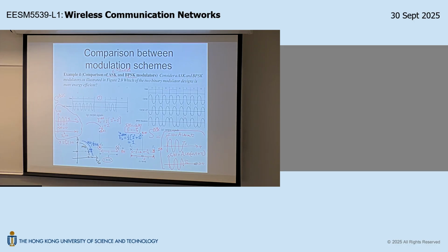So now if I have a design that the 4 points are like this, which is just a rotation, what about the performance between these 2 designs? What can you say about the performance? Which one is better? So the difference between these 4 points and these 4 points is the rotation, right? Is there any difference? When I say which one is better, that means under the same bit rate, same bandwidth condition, which one requires more energy to maintain the same error probability?